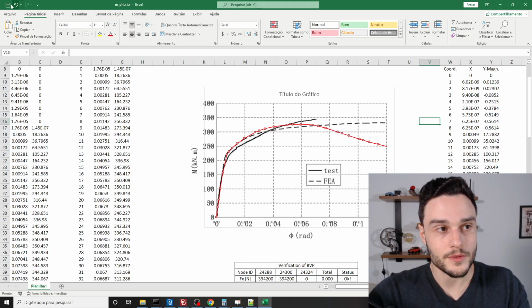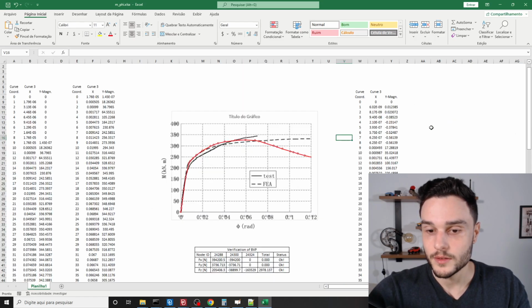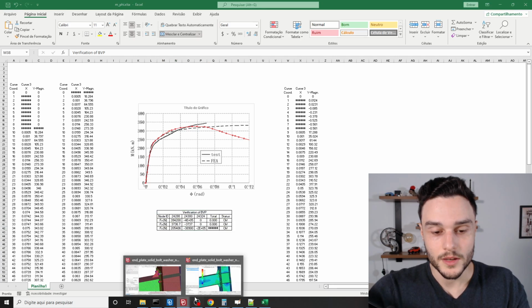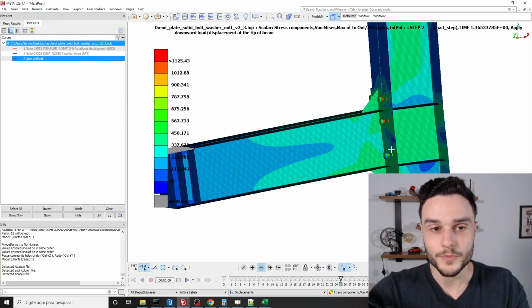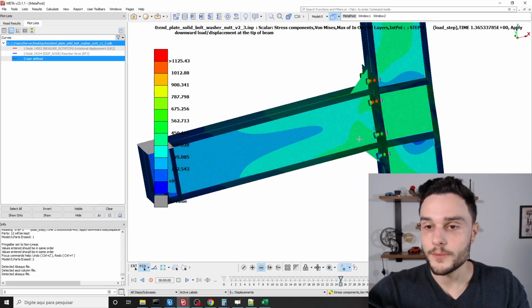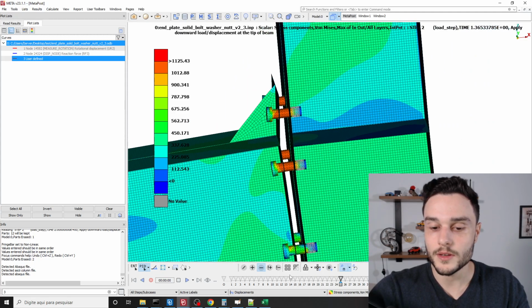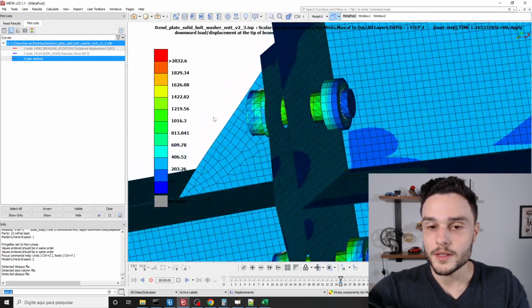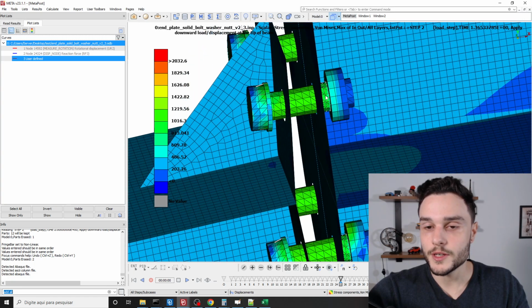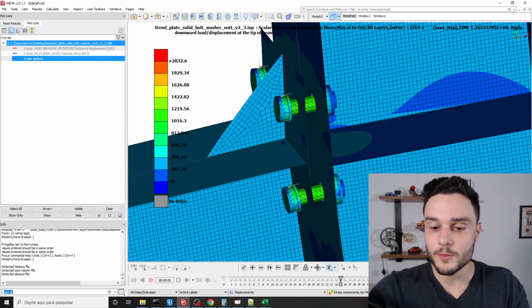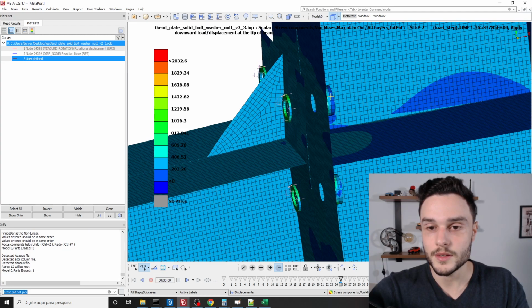Okay, so this is one thing that we need to do. Let me return here. Guys, let's see how this bolt pretension works. Let me click on show all. And now let's see how this bolt pretension works. You're going to see that this nut moves to the left. I'm going to use the nut function, PID selection mode, select bolt and washer.